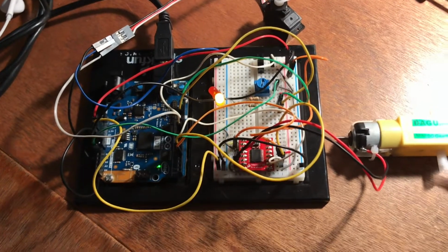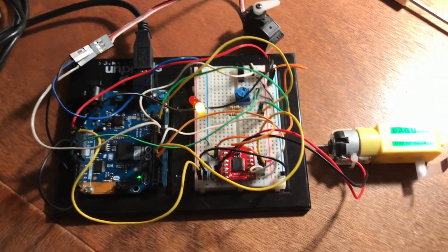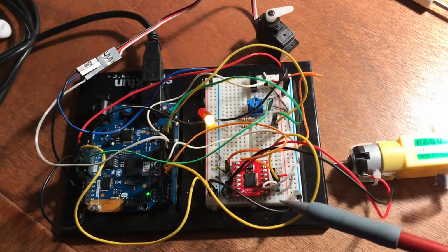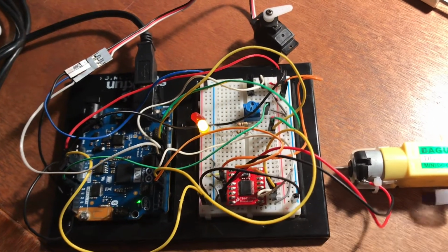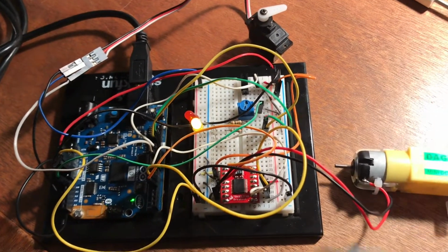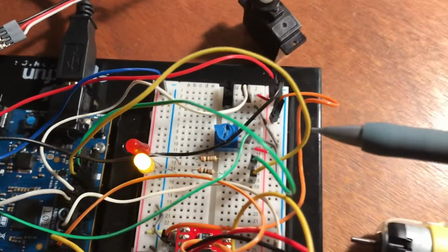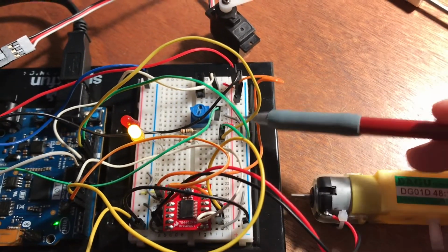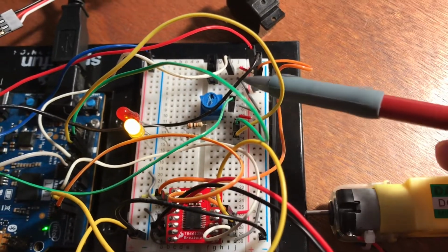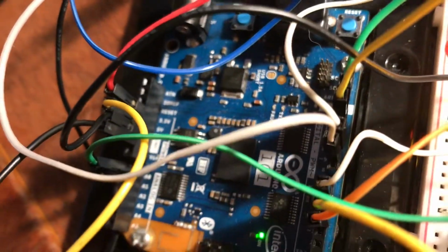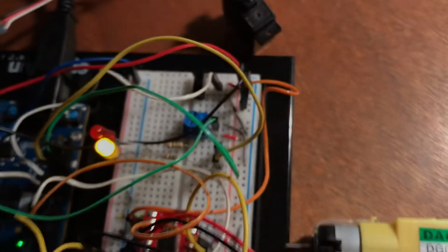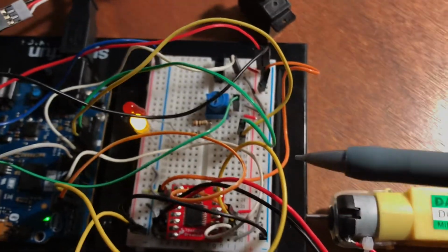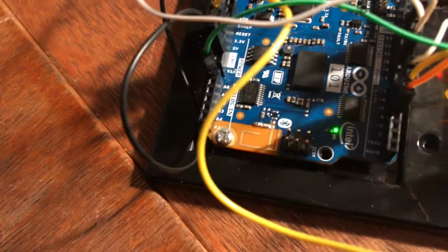This is a modified Arduino board for the modified code of a motor driver with inputs. Here we have the motor driver, same as the basic code. All the wires are still the same, still grounded the same way, and the motor is connected to the same pins on the board. The potentiometer and the switch are still set up the same way. They're both grounded by these gray wires. The red wires are both still connected to the 3.3 volts. The white wire is bringing the switch to pin 10, and the green wire is still bringing the potentiometer to analog pin 0.